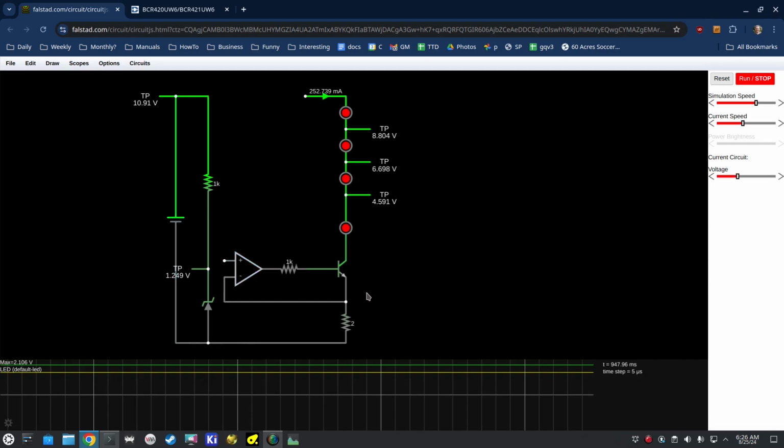So this is a feedback loop. Whatever voltage is here, if these voltages are different, it's going to drive this up or down. So say that's higher than that, then this is going to go up, right? And as it goes up, this is going to let more through, which is going to increase that, which is going to push that up. And if this is down, this is going to be less here, and that's going to make that go down, and that's going to make that go down. So it's a feedback follower. So that part's pretty good.